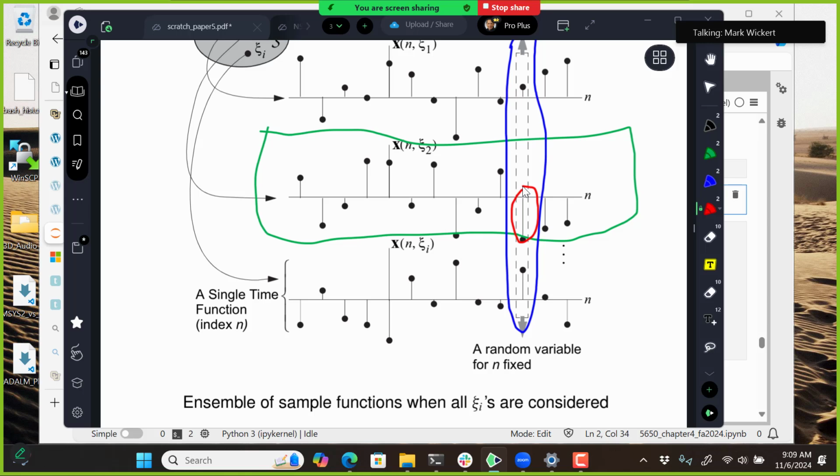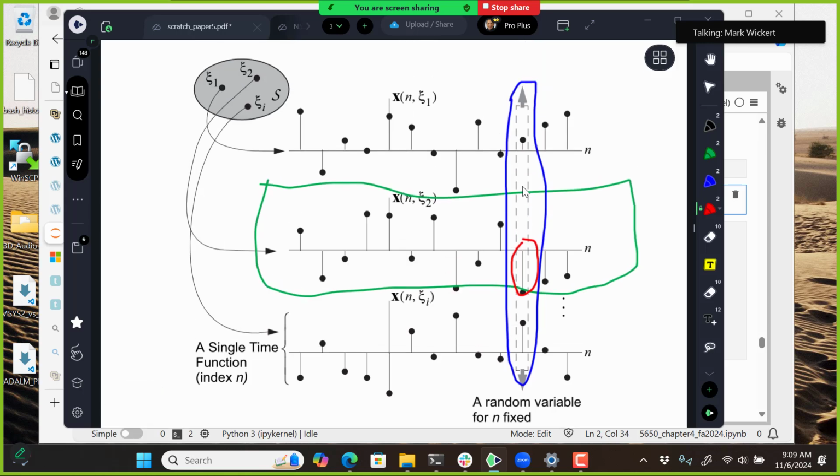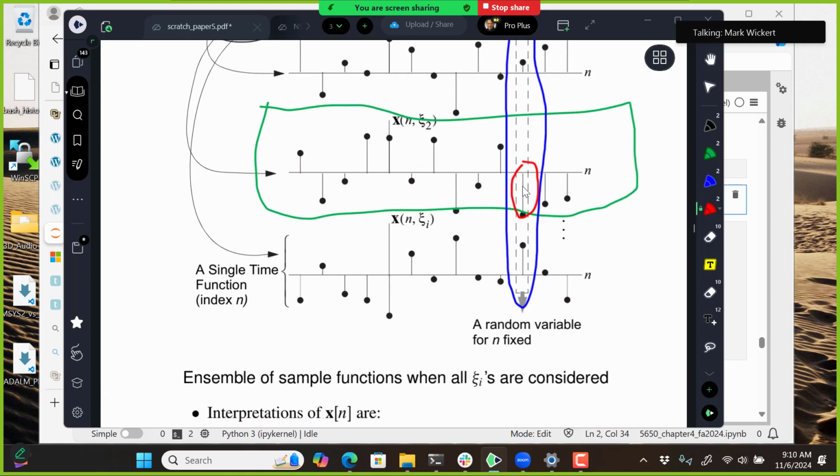These interpretations, for the first time viewer of random processes, seem kind of overwhelming, that you have to think in this large sense of having this ensemble that contains an infinite number of waveforms. Now, this idea was created by man to model randomness in nature or electronically generated by some other signal coming at us. So, is it a necessity that we have a random process model? No. Is it convenient and useful? Yes. So it's put up as a useful modeling tool to try to understand and represent things that our system is going to have to deal with. So the ensemble just gives us lots of flexibility in how we characterize things, and then how we consider the interaction with a system and a random process.